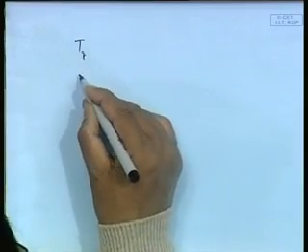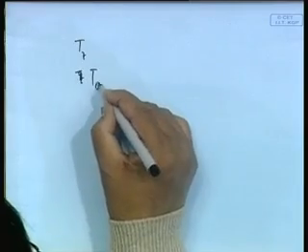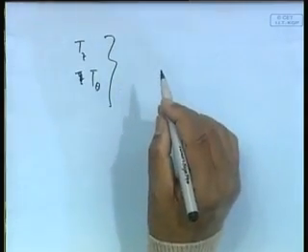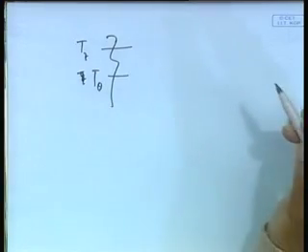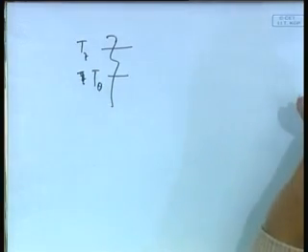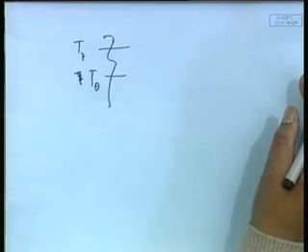Okay, I still have a few minutes for this, and I want to touch upon, not a problem, but one more thing, this relation between Tz and T theta from design point of view. You see, what would be your objective in a design? Would you like them to be same or different? Obviously, our aim would be to make sure that they are separated out, because if they are not separated out, I am going to have, when it is excessively heaving, also excessively pitching.